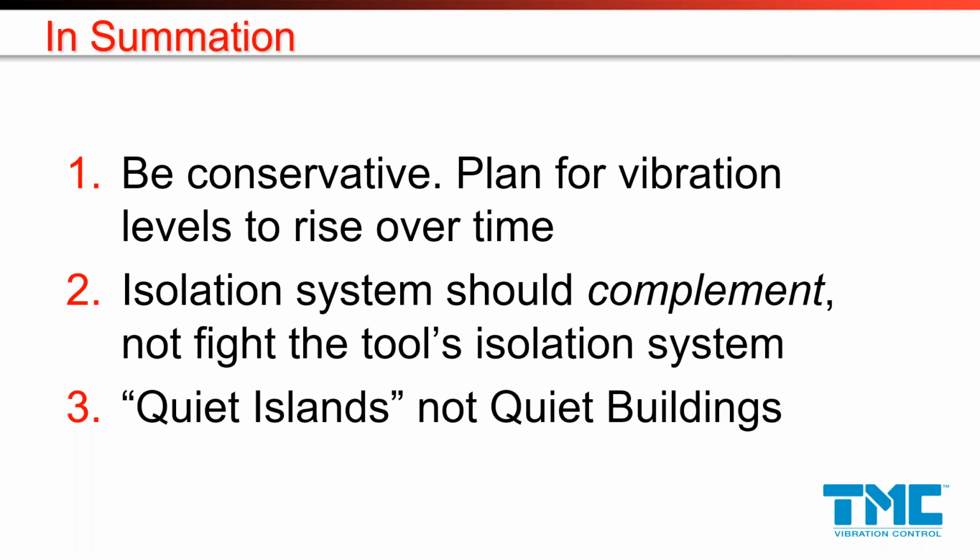Okay, thanks. Does an 18-inch raised access floor provide adequate clearance for most isolation pedestal systems? I would say yes, that's probably the minimum. I would prefer 24-inch. I think it just gives a little more room down there. But I would say 18 probably would be able to handle any commercial system.